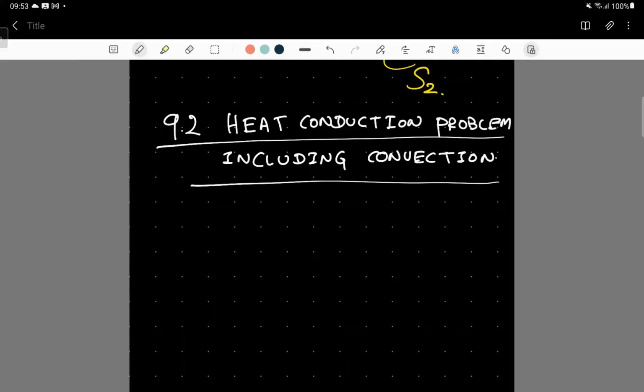If an external pumping or external force is used to induce a flow, then it's a forced convection. And if no external forces or flows are present, then the convection takes place due to natural buoyancy forces, due to local temperature differences. We call it then natural convection or free convection.